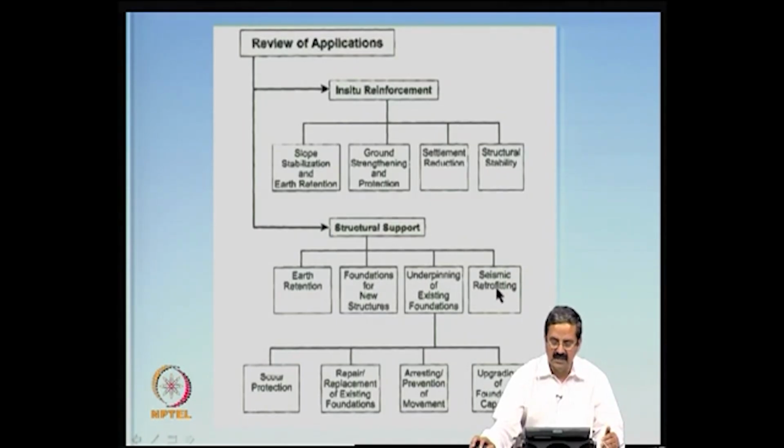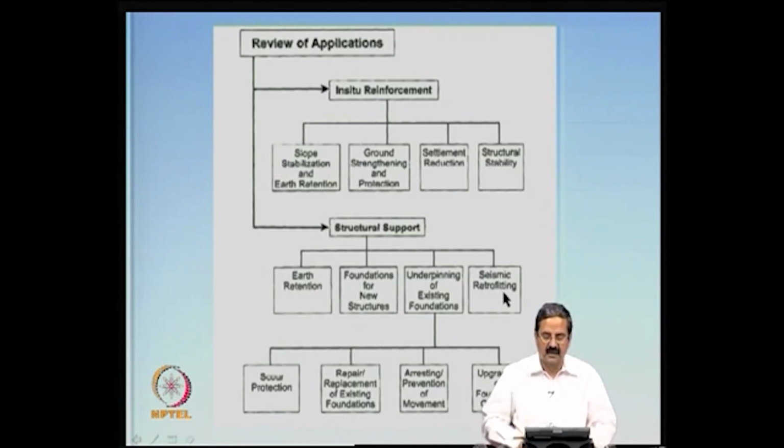Then seismic retrofitting. In fact, the other day I was mentioning that micropiles were used in one of the dams in Bhuj, when the Chang dam failed during the Bhuj earthquake. When they did the reconstruction to increase the liquefaction resistance, they used micropiles in the foundation of the dam. All along the foundation of the dam, micropiles were used.